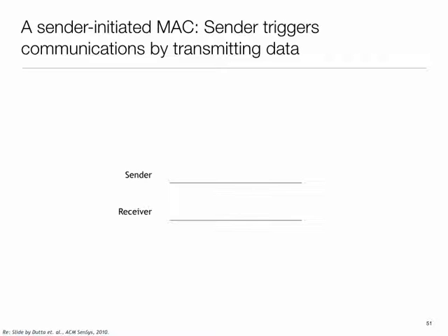Okay, now not quite, but we can code packets in a certain way so that when packets partially overlap, I can still kind of end up recovering. So there have been papers around these ideas where now you have radios which basically can let packets collide and still recover them, under some conditions with certain constraints like these. But the first idea, which is if I have basically identical packets, if they're perfectly synchronized in time, then there is no collision happening. So it turns out that idea got used, and there have been a few MAC protocols which are not standard, but probably may someday be part of the MAC standard.